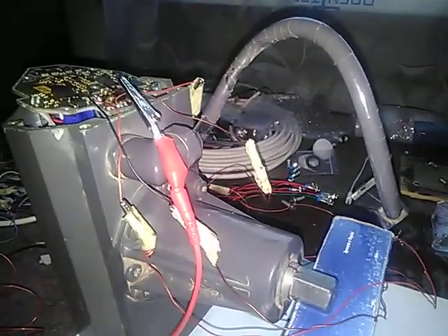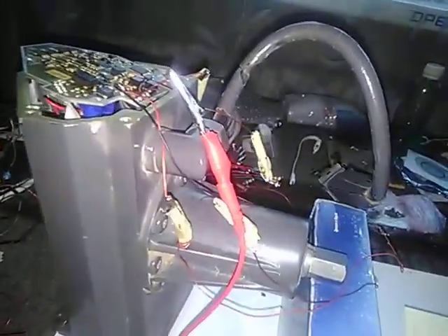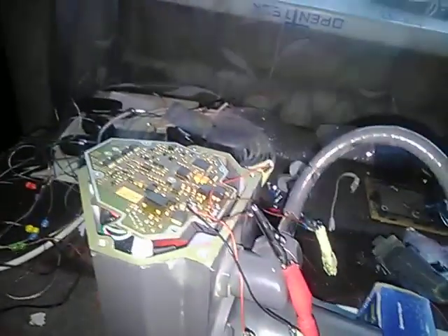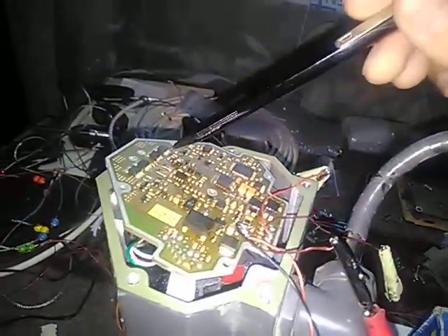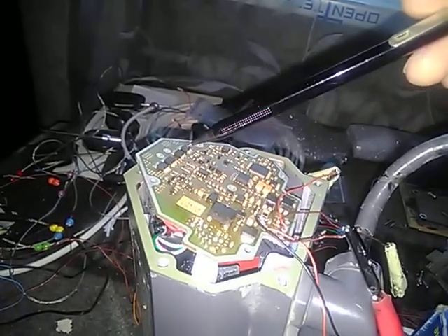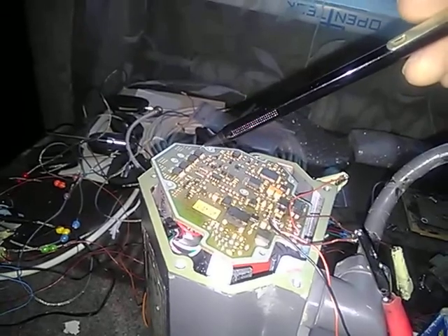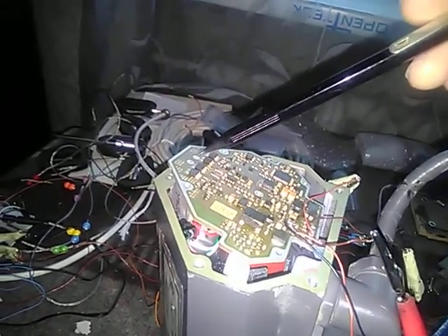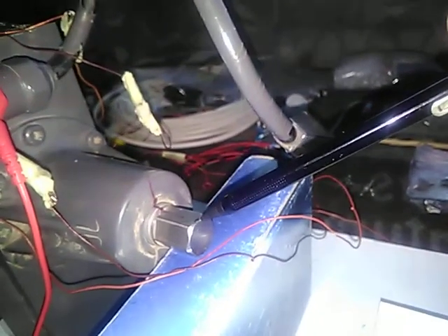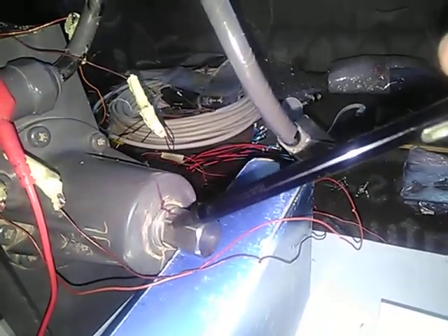If the operator pulls the joystick to the rear gear, we have the same by CAN bus. The corresponding signal is delivered to the processor, and another map of potential is activated on these four switchers, and a current of another direction rolls the shaft counterclockwise.